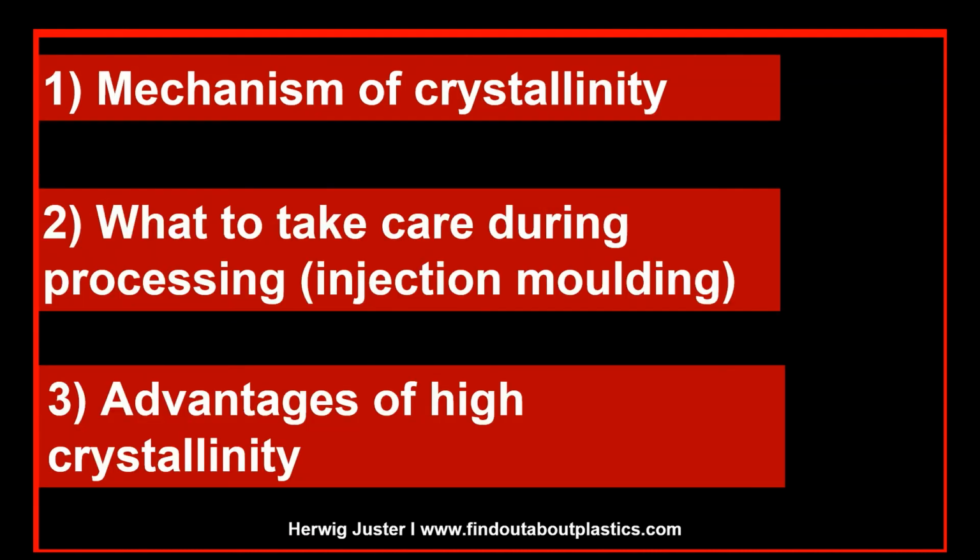Okay, so to summarize and to conclude, polymers such as polyethylene with a glass transition below room temperature can handle colder mold temperatures better than engineering polymers, which have the glass transition above room temperature. And so in this case, cold mold temperature will result in lower crystallinity and problems with part performance. So you have to find the optimum crystallization temperature between above Tg and below the melting point to have a good molding process itself, and then also good part performance.